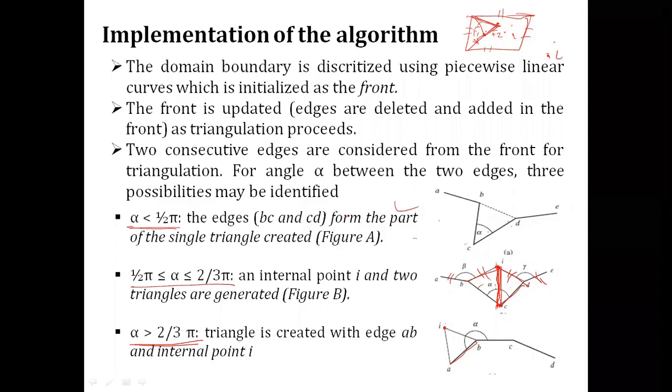So now you create a new seed point and join the line that is extending or creating the obtuse angle. You start to create small triangles and basically change the direction of the front as it moves in different directions. Now, what will be the sequence of operation? The sequence of operation is not defined, but generally this algorithm works so that if you have this condition, you try to convert it into this condition.